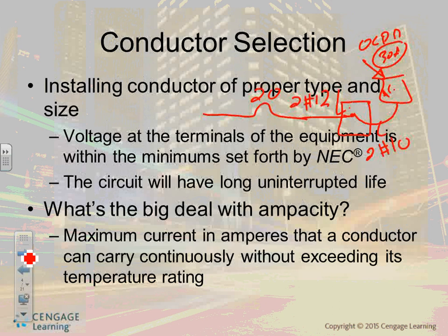So, like in mine though, that whip going in there, the red, black, and green. Yes, the green is the ground, but there's no red, black. Yep, black, black, and the red will go to the re-identified white, and black goes to the black, and you're good to go. What about the quick ground? The green goes to the green. Inside the box, are you wired with cables? So they tie the ground to the ground, inside the box.